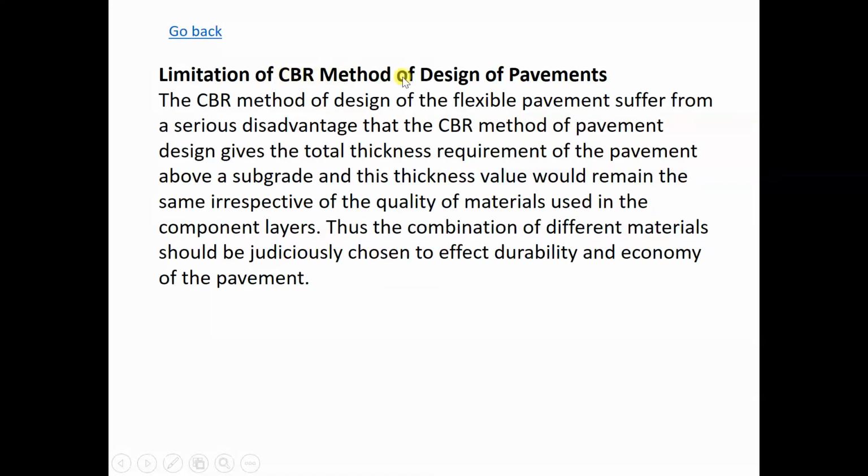Limitation of the CBR methods of pavement design. It has a serious disadvantage: the CBR methods of pavement design give the total thickness requirement of the pavement above the subgrade, and this thickness value would remain the same irrespective of the quality of materials used in the component layers.